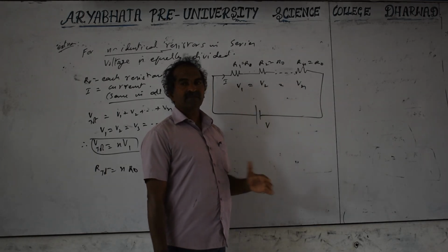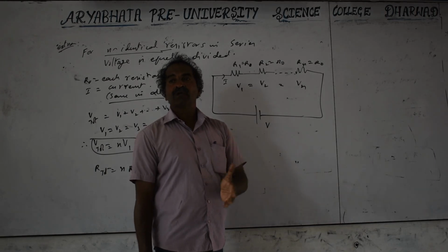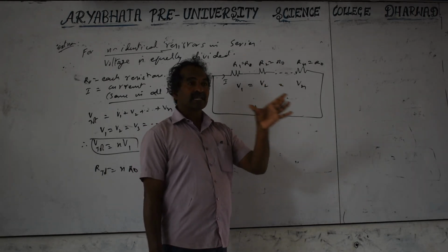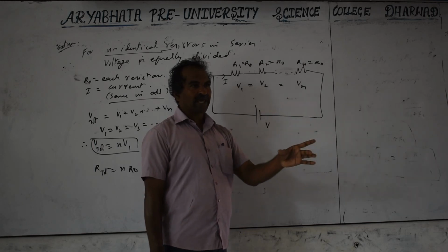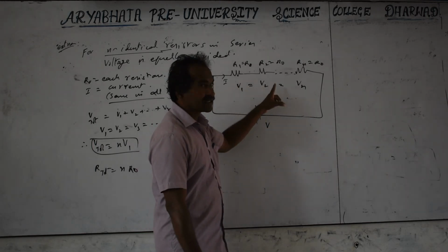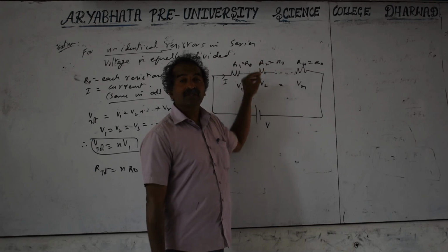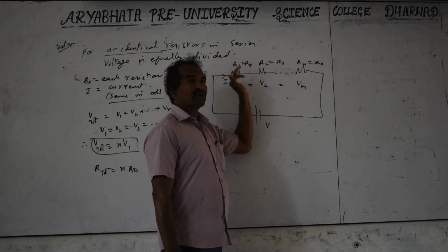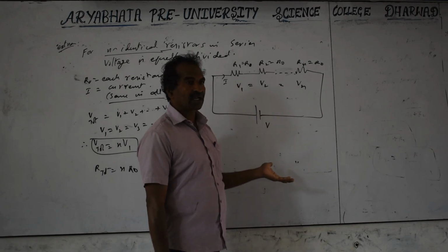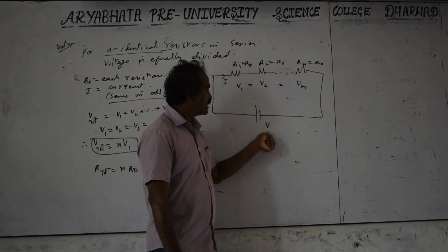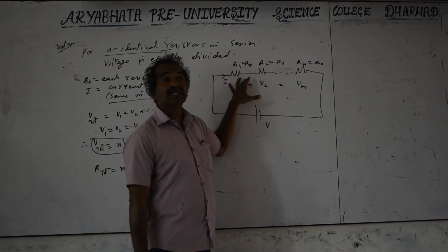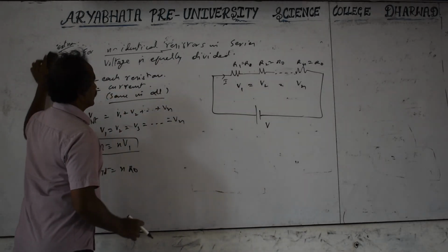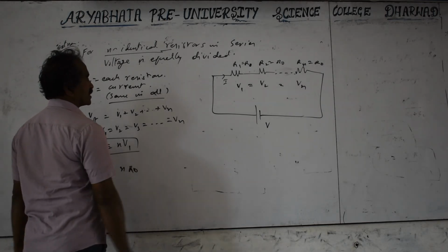So in such a case, if the device is not able to withstand the required voltage, then you connect some resistance in series. Another device or other electrical resistance, some electrical wire, a 9 kilo ohm resistor, etc., you can connect in series, of the specific resistance you have to take. So that the total voltage V equals V1 plus V2, and for the device the voltage will be less than or equal to what it can work with, and less than the total voltage, so that the device will not be damaged. So voltage is divided in a series combination.